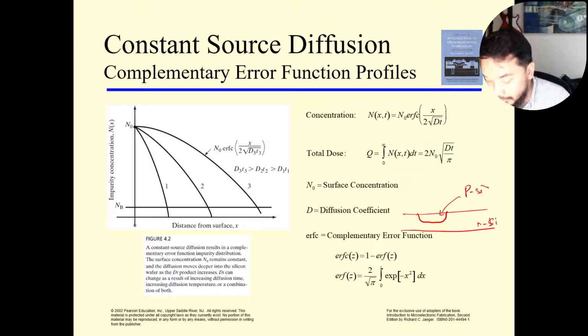Okay, so this is when you have to cover this portion with a mask or your barrier layer, and then you deposit on the surface your p-type dopant, and then you carry out the diffusion so that the dopant atoms will diffuse into forming the shallow junction within the n-type silicon wafer, leaving behind a shallow junction.